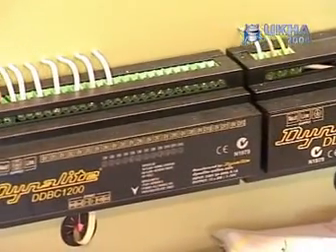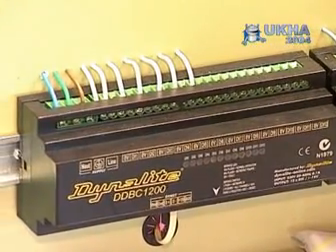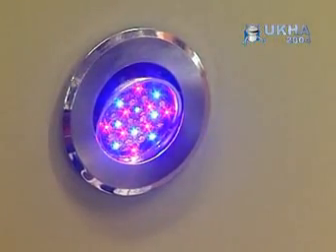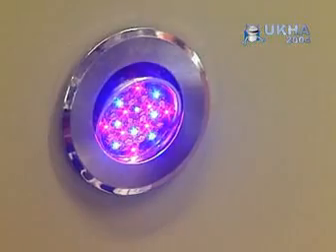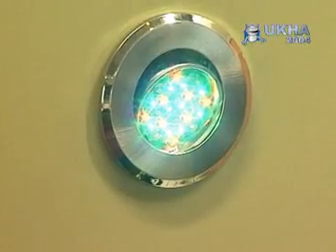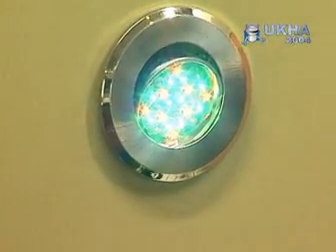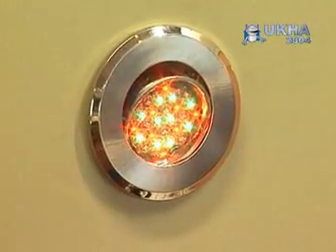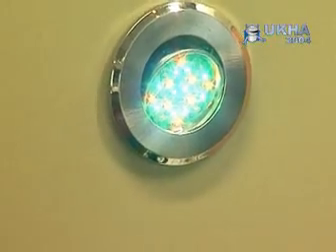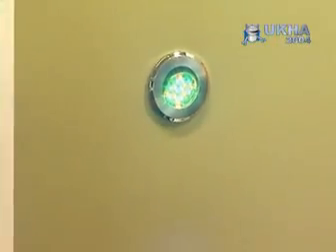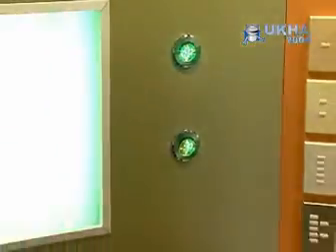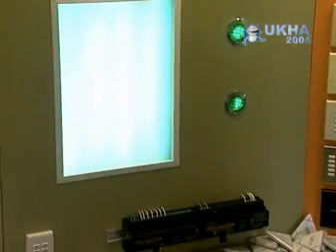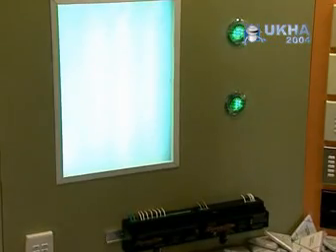We've got our DIN rail mounted D-LED C401, 4 by 1 amp maximum LED controls. These directly control luminaire fittings. They can be 12 volt or 24 volt configurable. The LED controller can control 48 individual channels. It can control 16 RGB channels to allow for colour mixing and chase sequencing and that sort of thing.